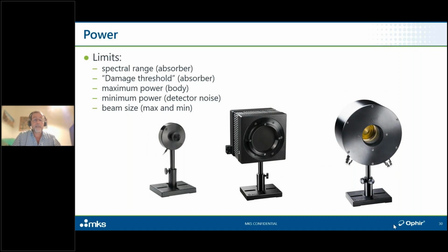The sensor in the middle, you can see that its body is designed as a sort of a heat sink. In some cases, there will be a fan there to give it an additional heat dissipation capacity. For higher power, kilowatt and upward, industrial applications usually will use water-cooled sensors, such as the one you see on the right. In general, in those applications, the lasers themselves are also water cooled, so there is usually going to be cooling water infrastructure at the facility.